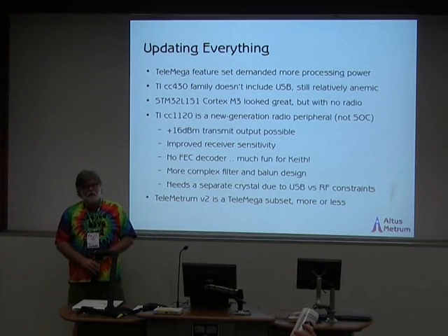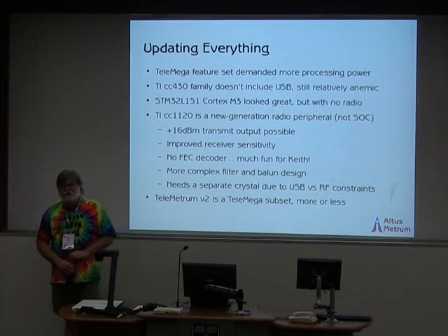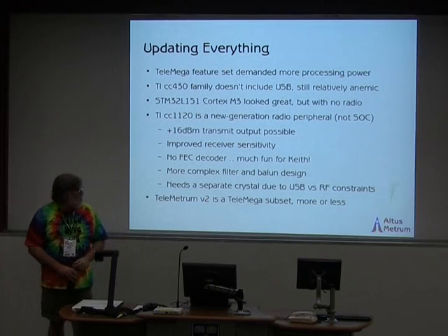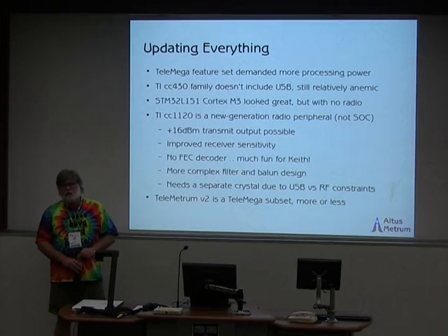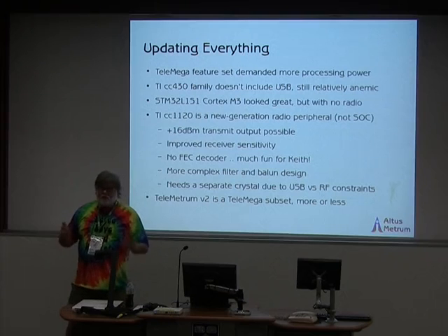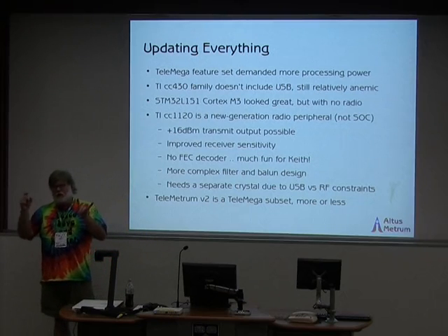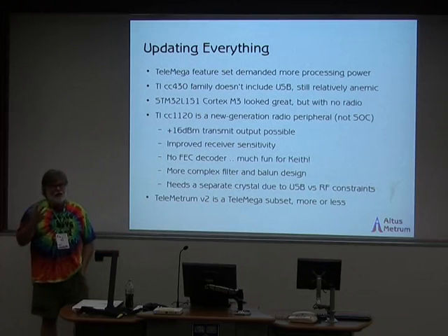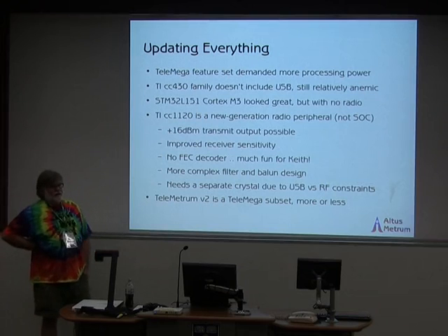So actually, a guy in the US came up with an interesting idea. He spent quite a bit of time analyzing sensors. It's all written up in Rockets magazine over the course of several issues. In the end, he basically did an inertial measurement unit design to figure out which way the rocket's oriented. Is it still going mostly vertical, or has it laid over for some reason? What he designed was a board that could go between your flight computer and the pyro charges to provide an extra degree of gating on whether to fire the charge or not. So it provided a pyro event inhibit if you were too far away from vertical. And it was called the tiltometer.